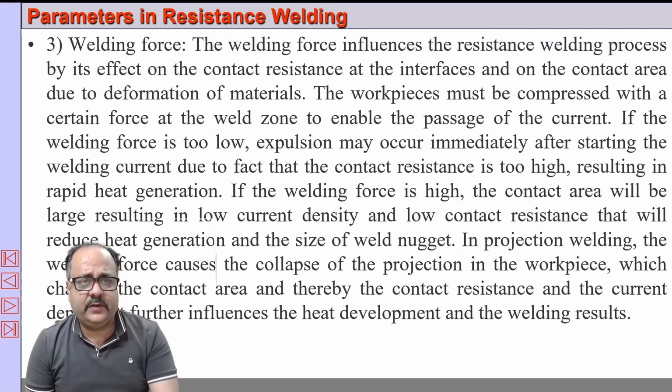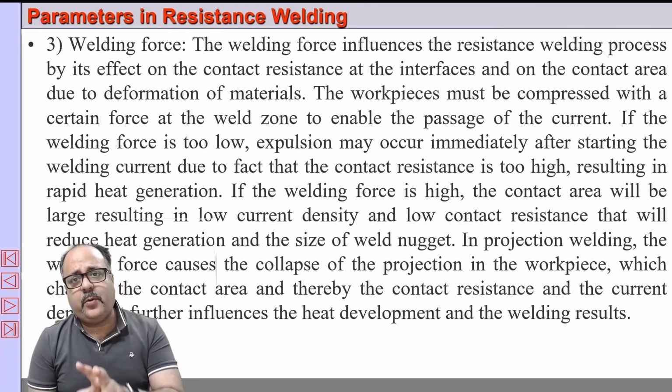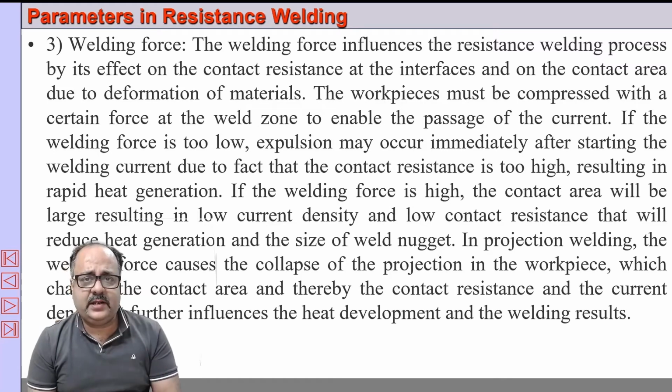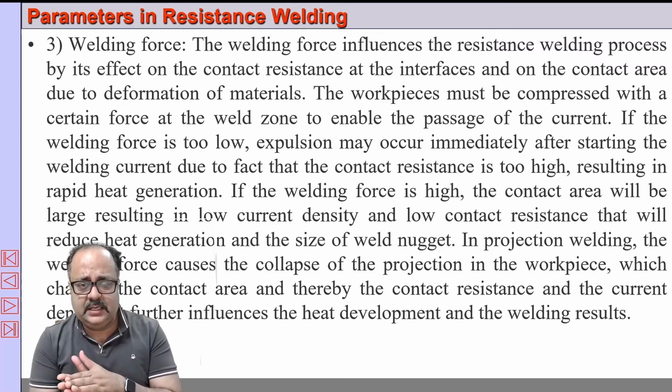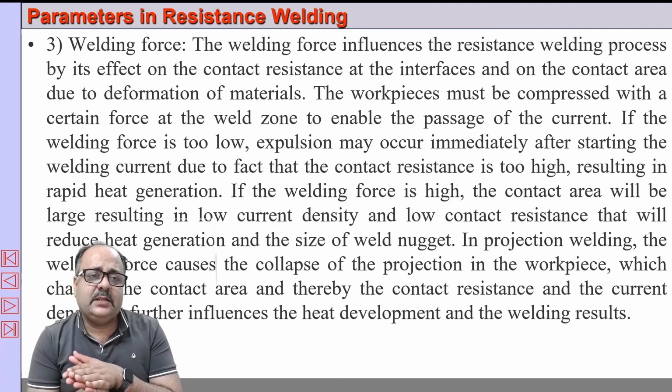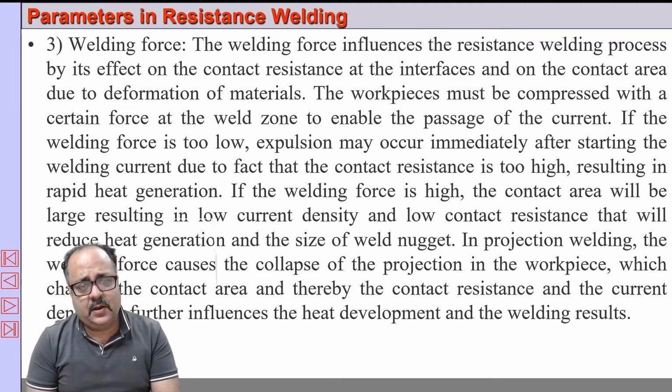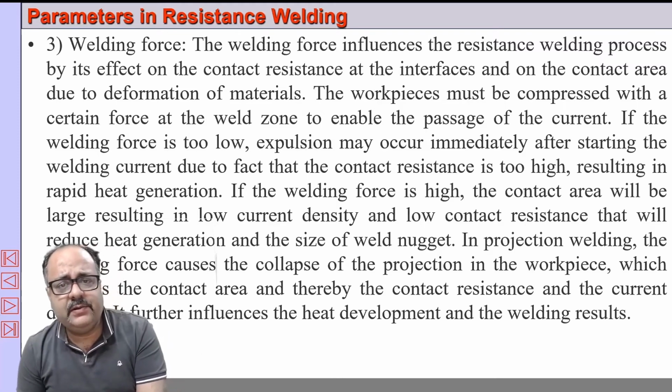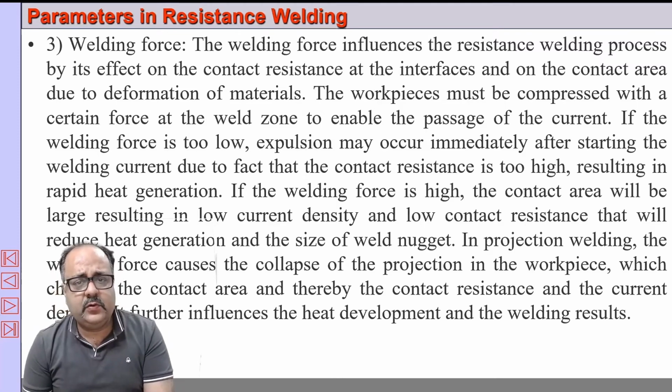Welding force is also very important. Welding force is important from two points of view. One is the contact resistance, and the other is the contact area. Of course, as the welding force is increased, the contact area also increases because the asperities will flatten out. And of course, if you apply more pressure, the contact resistance will decrease.